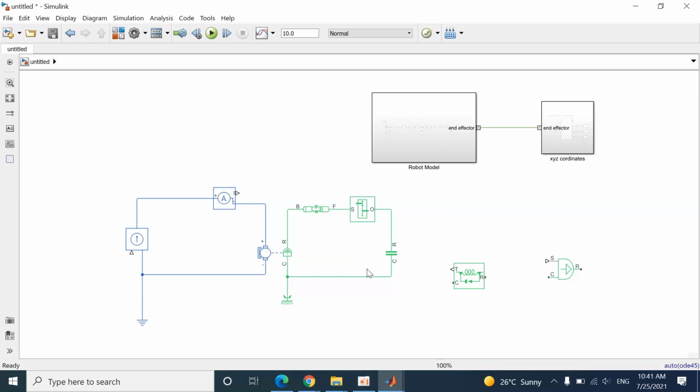Here we can get our output now, but if we connect 2 sides of the output to the ideal torque sensor, the torque of the motor can be measured. That torque will affect the robot motion, but we need to define the effect of the robot motion on the motor too. We will do this by defining a constraint.